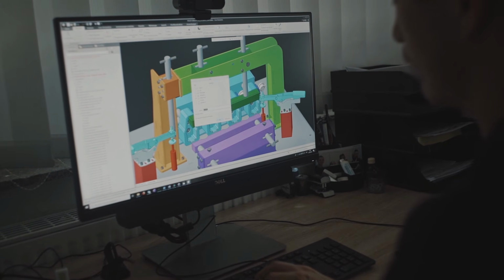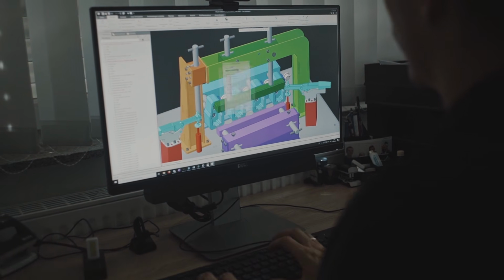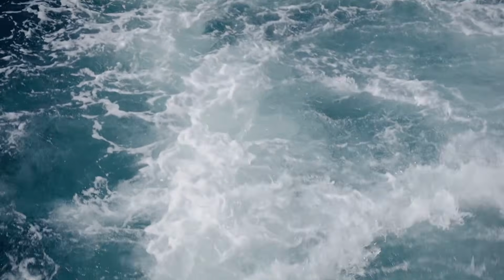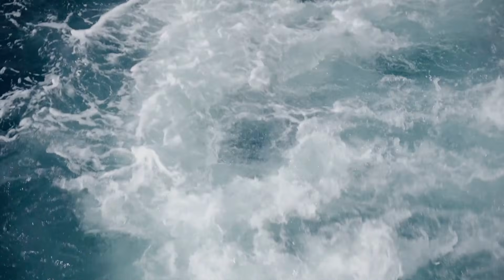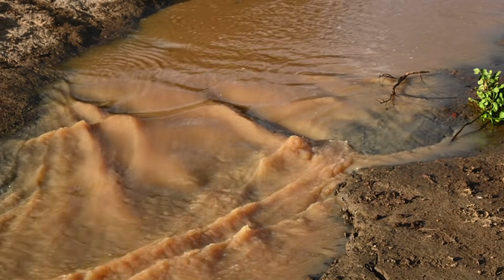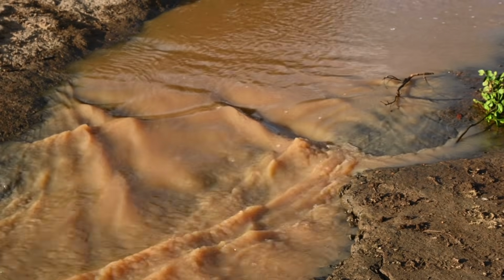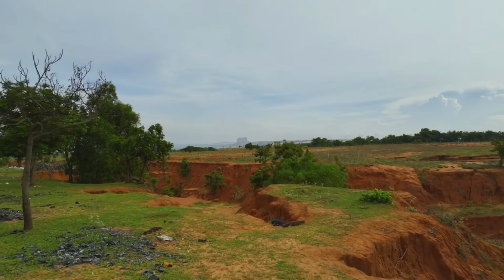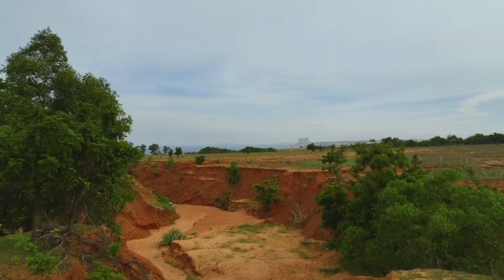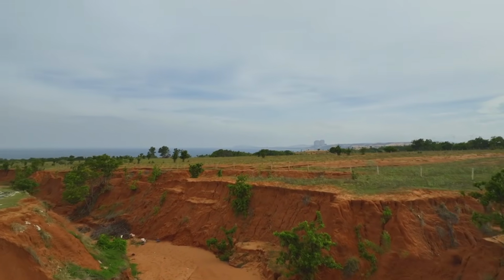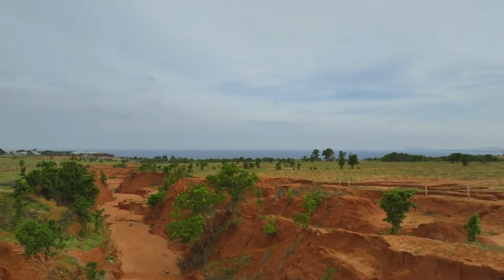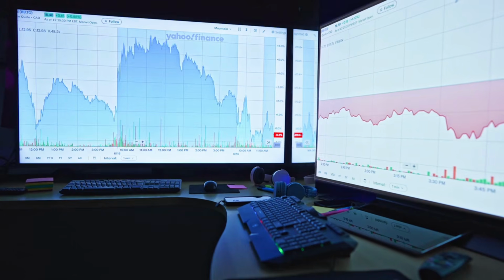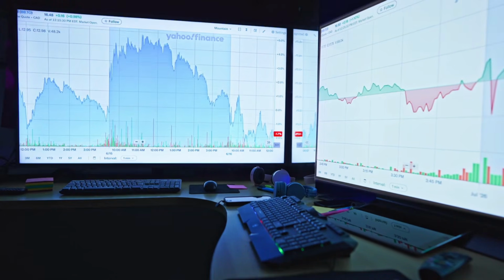The complexity of this wave is further deepened by the sheer variety of ways a dam can fail. If a concrete gravity dam tips over, the release of water is different than if an earthen dam erodes from within. In an earthen dam failure, the breaching process is gradual but accelerating. As water overtopped the Teton Dam, it began to carve a small notch. That notch increased the velocity of the water, which increased the rate of erosion, leading to a feedback loop that widened the gap exponentially. This means the dam break wave isn't a single event, but a growing crescendo of force.